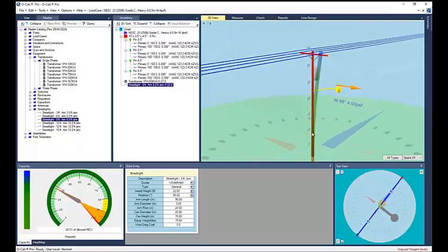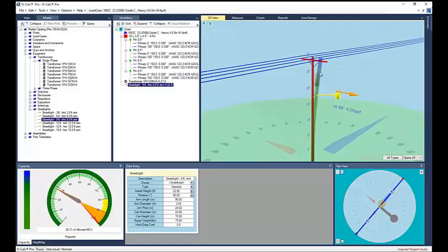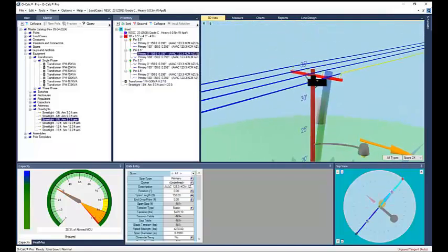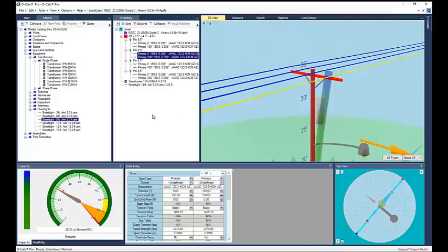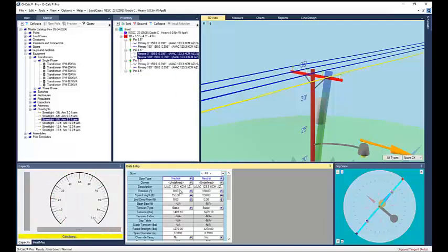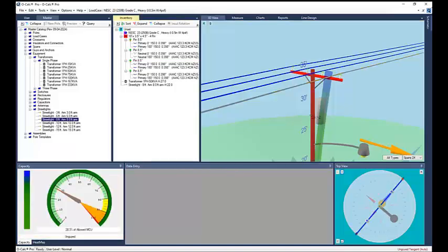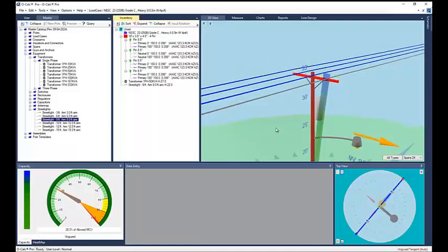Now additionally, if I intended to have one of these conductors represent a neutral, then here in the span in the data entry, if I hold down my shift key, click on the word primary, it draws a blue box around both those fields, and I'm able to come in and quickly transition that to being identified as the neutral. Notice your neutral wire is gray then.